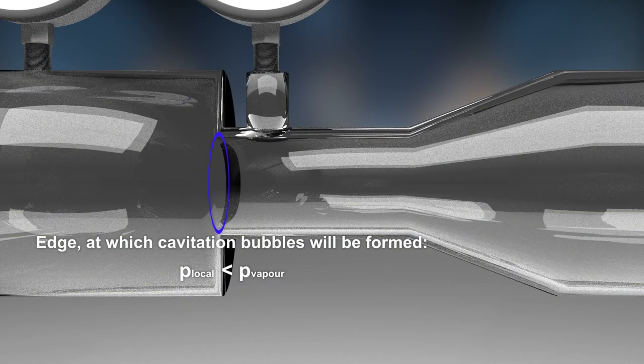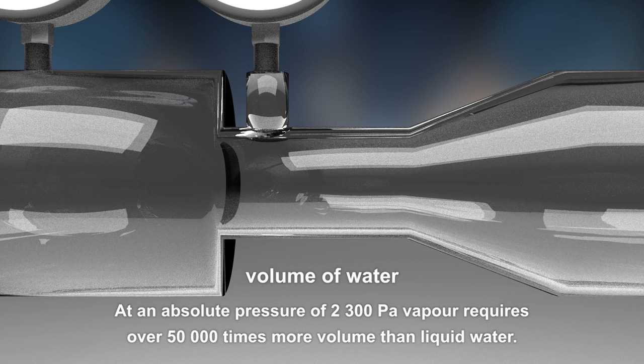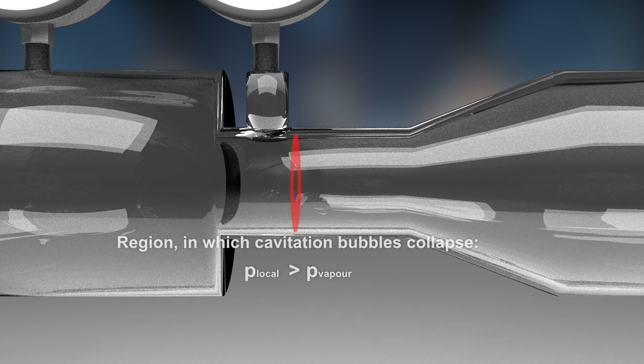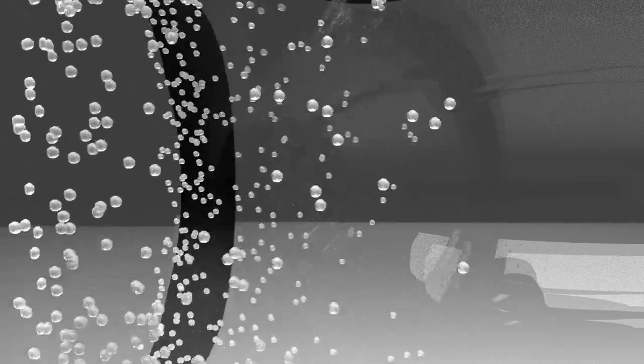The low pressure at the exposed edge causes cavitation bubbles to form. At a pressure of 2,300 Pascal, a certain mass of water vapor requires over 50,000 times more volume than in its liquid state. The bubbles collapse as soon as they reach a region with a pressure above the vapor pressure. Because water from the vapor bubble occupies 50,000 times less volume after having condensed to its liquid state, the collapse of each bubble is a spectacular event and emits pressure shocks.